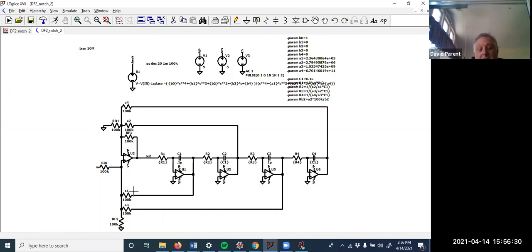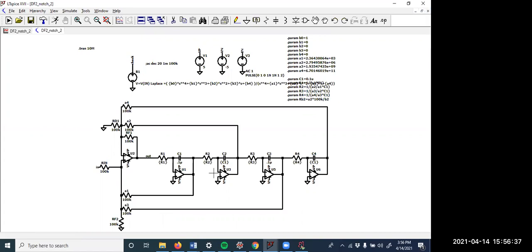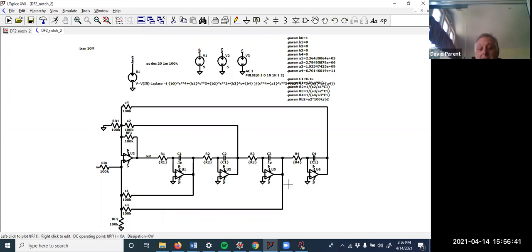So I keep it inverting. Inverting times inverting is non-inverting. I need to make sure it's being subtracted. So I come in on the negative side. But now I have 3. It's inverting. I want to keep it that way. So I come in on the positive side. And then here I have an even number and I come in on the positive side. All right.